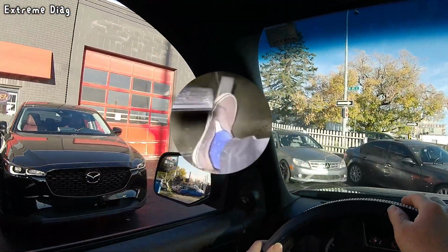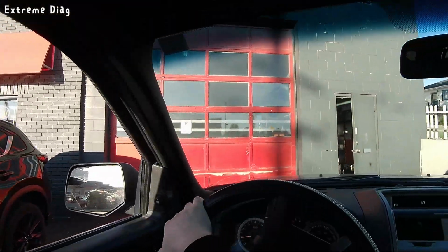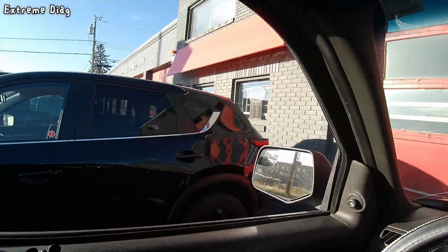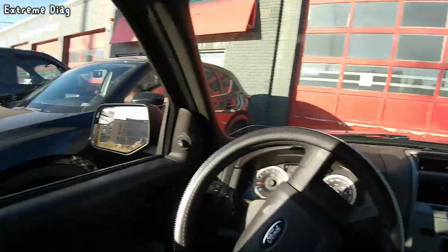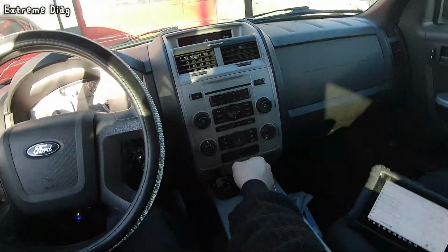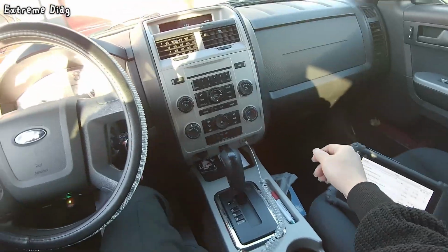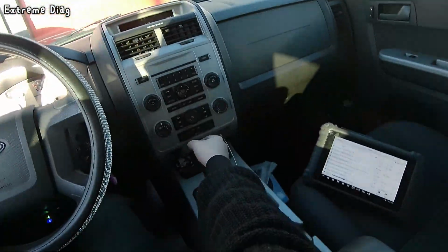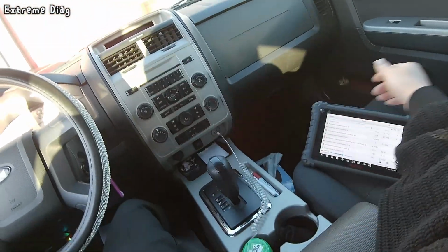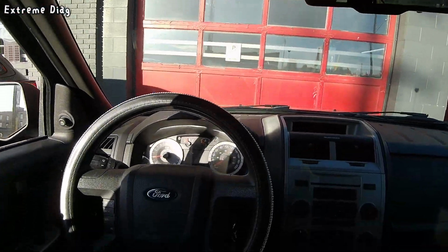Right now, I'm pressing the accelerator pedal all the way down to the floor, but the car won't go any faster than 10 km per hour. This is called default mode or limp mode. When there's an issue with the acceleration control system, the computer significantly limits engine output to prevent unexpected situations like sudden acceleration. In this mode, the car barely has enough power to pull over to the side of the road. It seems like the customer is asking us to fix this symptom, so let's move on to the next step.